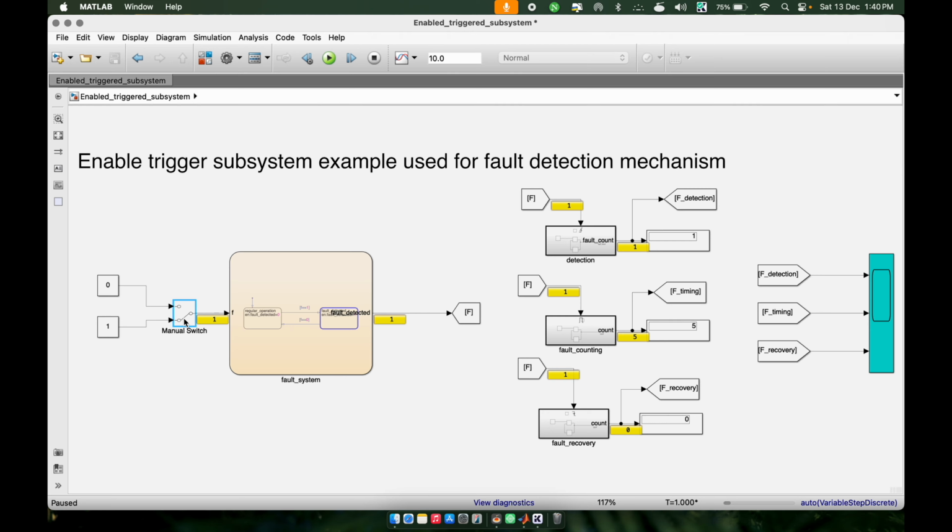Okay, so now let's remove the fault, right? Now we removed the fault, and if I step, you can see the value is staying as 5. This value stays as it is because now it is deactivated, but we have selected the option for held. And over here, you can see the falling edge got detected, right?